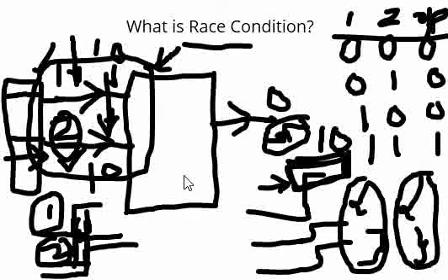So in those scenarios, it is important that we bear with those conditions, because we know that it is happening. But in dynamic race condition kind of scenarios, we have to eliminate those delays, and these delays are not just related to the PCB trace length difference, right? There could be some other devices in between, like buffers or some mux or some level translators, which are also causing some delays in the hardware.